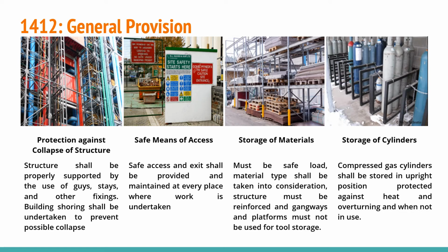Storage of materials. You must ensure that your storage unit is capable of carrying the intended load. It must be reinforced and follow the guidelines. And next is storage of cylinders. Compressed gas cylinders shall be stored upright and protected from overturning and heat when not in use, for the safety of everyone.